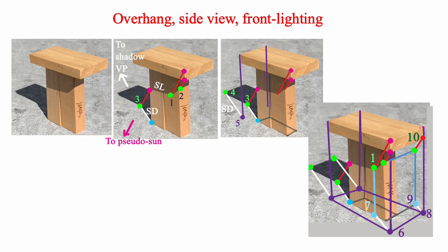To find the shadow on the ground, start with the light ray from the shadow line going down, where it intersects the shadow direction from the corner of the block is intersection 3. Then set up a seat so that the shadow direction is parallel to this first one, and where it meets the light is intersection 4. Now, what about this shadow line? We'll have to use this seat number 6, and light ray from the top of it goes to number 1. The line here goes to the base of the box and then up, and then intersects the light at number 1.